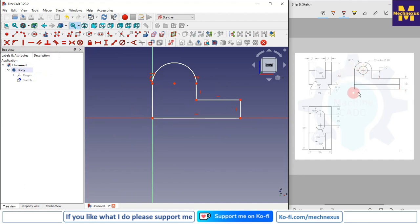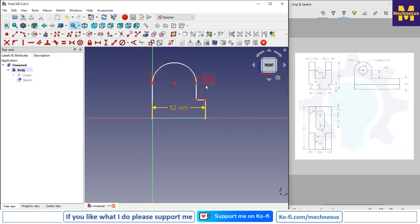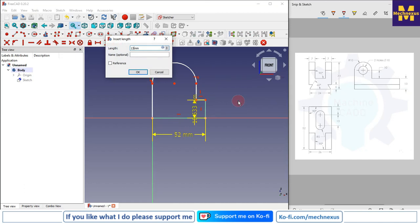So the total length of the part is 52, which we can see here. So I will select this line and I will give my dimension 52. Height is 13, so I will select this line and give my vertical dimension 13.